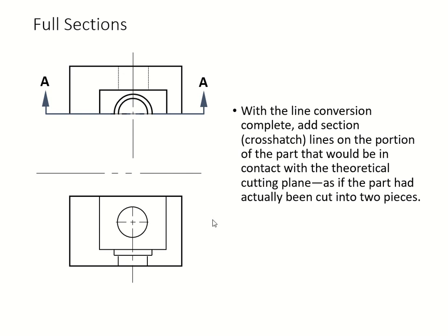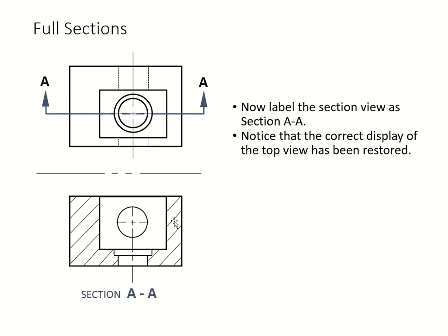Then we're going to complete our front view by adding our crosshatch. You need it. Don't forget 45, 30, and 60 degree angles. Here we're doing a 45. So, section A-A: hidden lines become visible lines. Your exposed area has been crosshatched, properly crosshatched, of course.